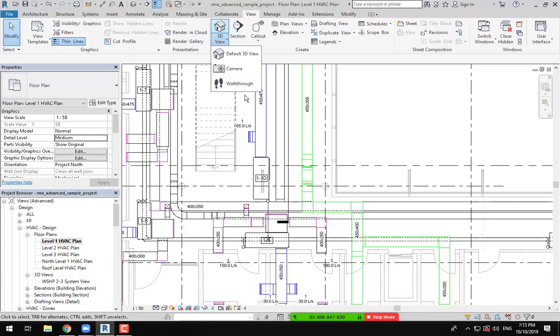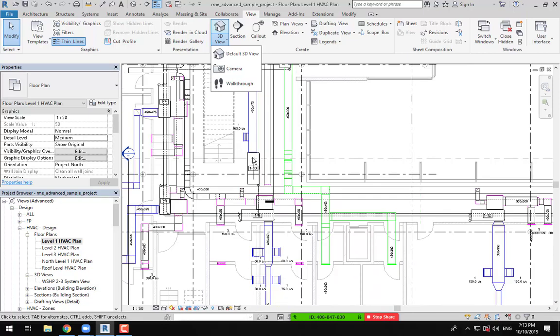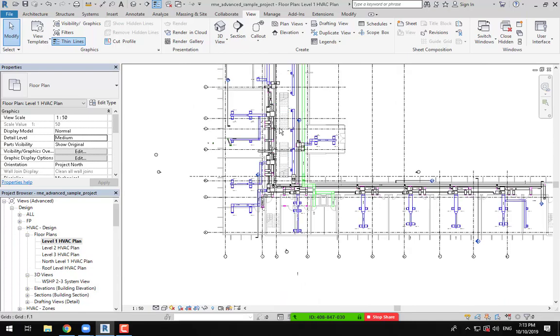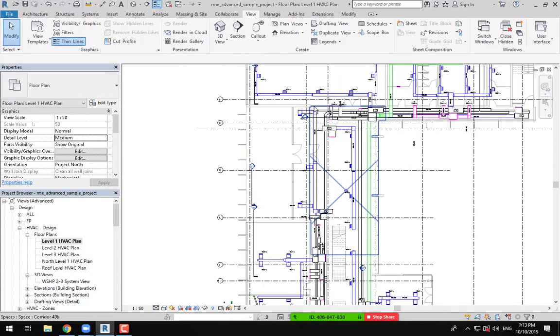The next command we will talk about is called walkthrough. Through this option, we can make a simulation, or we can make something called camera snapshots. It's many frames of camera, and we will combine these frames to give us a walkthrough video. How can we use this command?